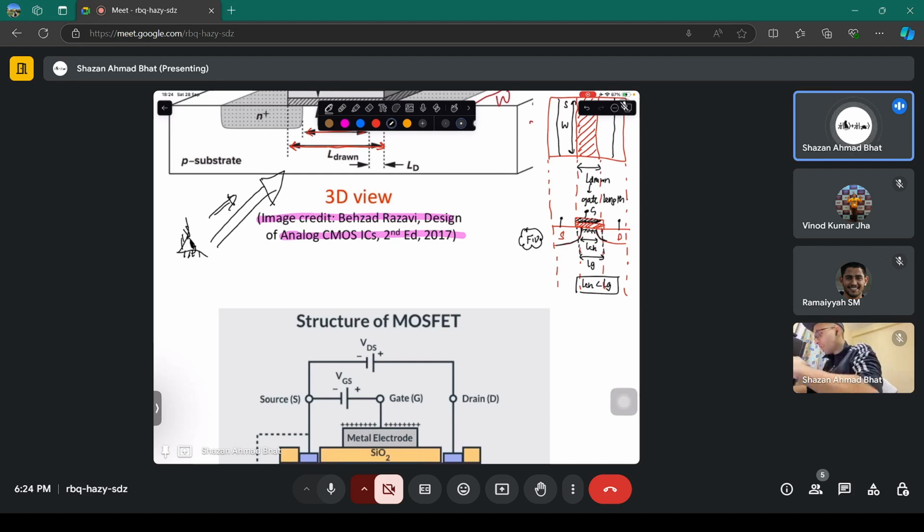Because the deposited layer over it, you usually cannot control whenever these source and drain regions are made. These are made by a doping process. These are something called highly doped pockets. Doping you cannot control to a very precision level. So whenever you make these regions, those dopants spread. If this is N plus, this is N plus, that means you have doped it with ND. This is also doped with ND. Those dopants spread in a certain fashion. It may be Gaussian spread, it may be Lorentzian spread, or uniform spread.